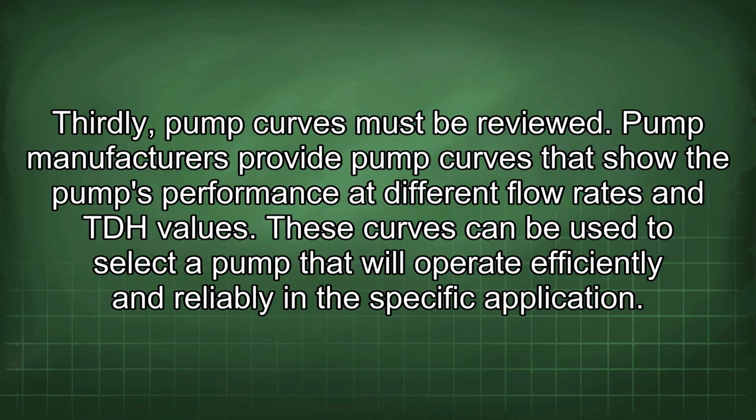Thirdly, pump curves must be reviewed. Pump manufacturers provide pump curves that show the pump's performance at different flow rates and TDH values. These curves can be used to select a pump that will operate efficiently and reliably in the specific application.